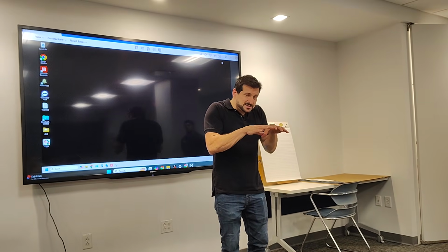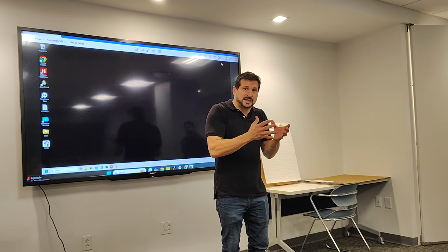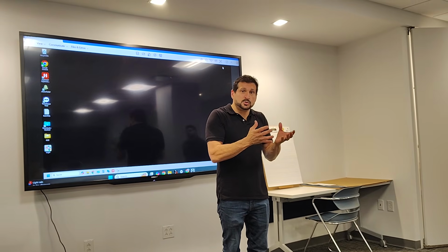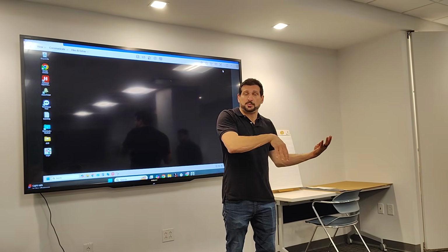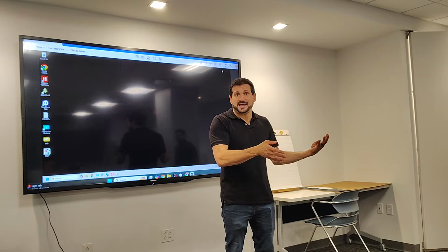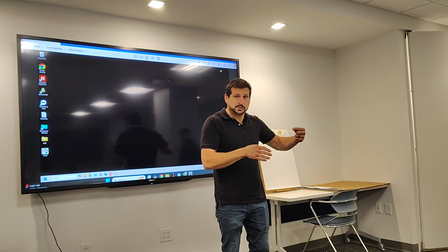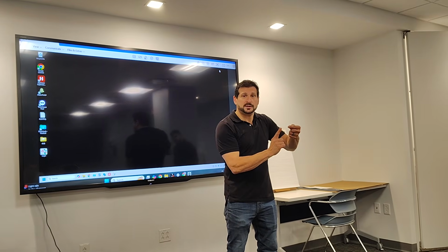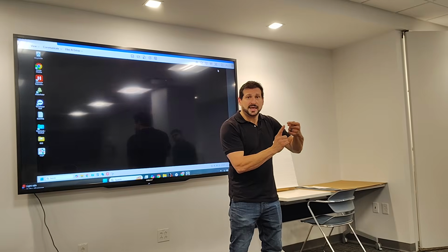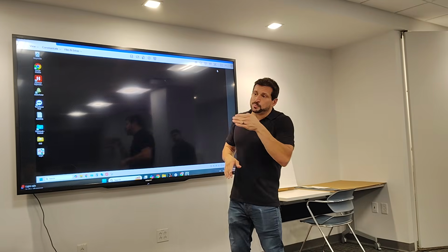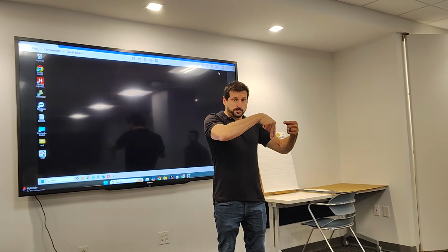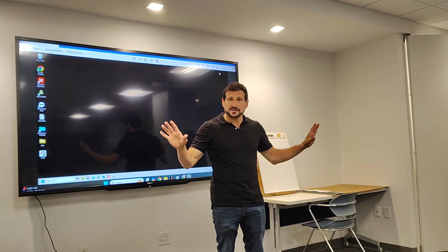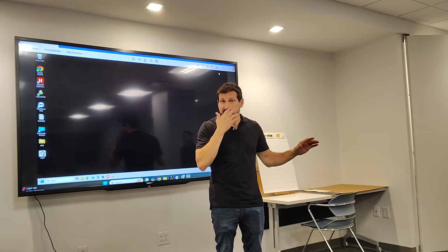Then inside of the controller, there's processing that occurs, and that processing utilizes those inputs, and it utilizes virtual points like set points. So I might measure a space temperature, compare it to a set point. Now I have this comparison, and I have to do something. Those points are outputs. So inputs, virtual points, outputs. Those are the types of points that you're dealing with on a BMS system.